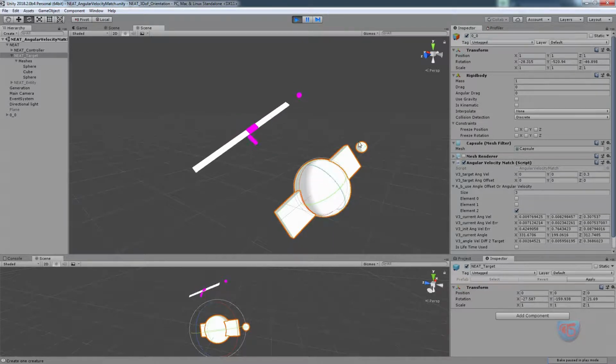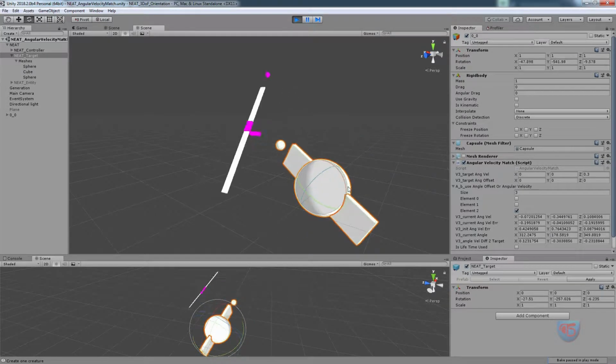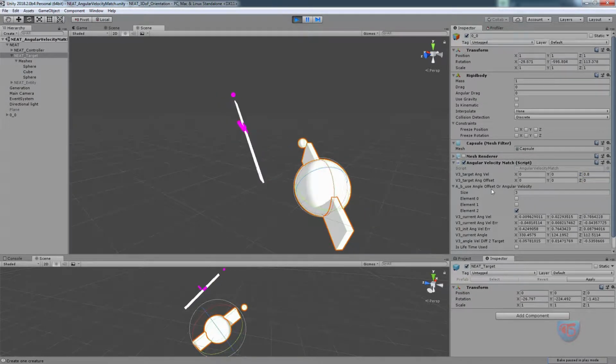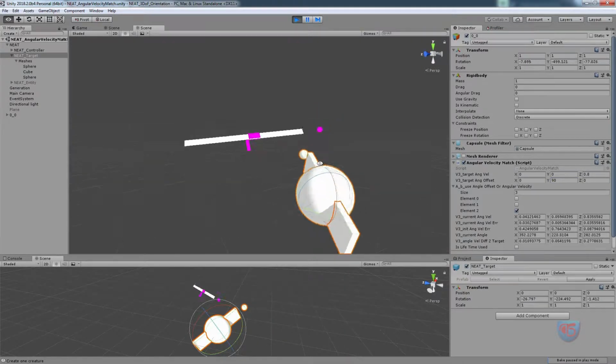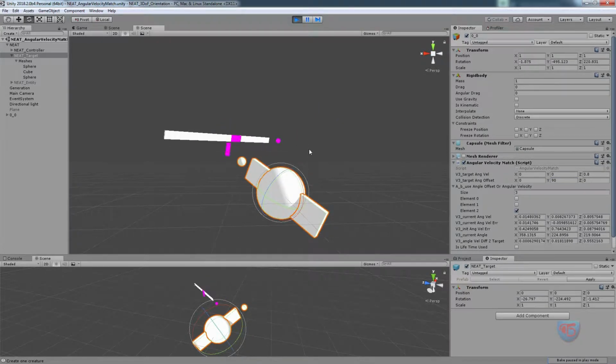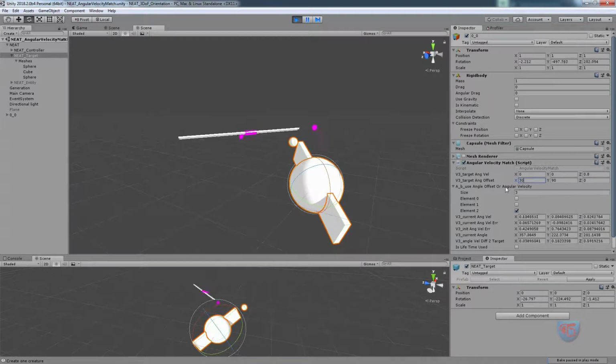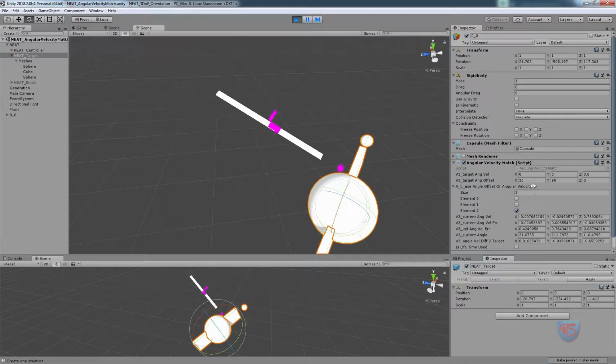More thrusters could possibly make it more responsive, or a more properly trained network could be even more responsive. Of course I can change the velocity, how fast I want it to rotate. I want to apply an offset, so it's 90 degrees with the y-axis toward my target, 30 degrees, or 25.4, whatever the angle of the x-axis.